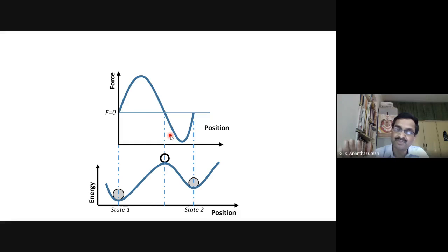Snap through, or we are pushing, that itself goes further. You don't have to do anything. That is the negative spring, so to speak. Positive slope is positive spring, and negative slope is negative spring. That is, you are pushing, and that will not resist your push, but go in the same direction. That's what happens in between, and then it goes negative for example sometime, and then comes back to the zero position. And this is the nature of the bistable structures.